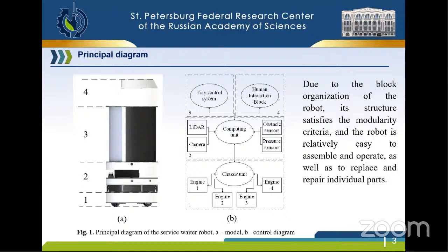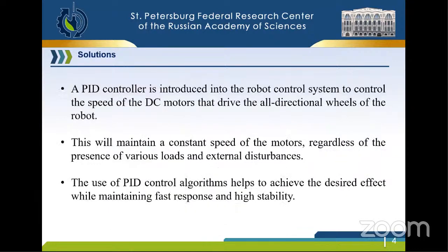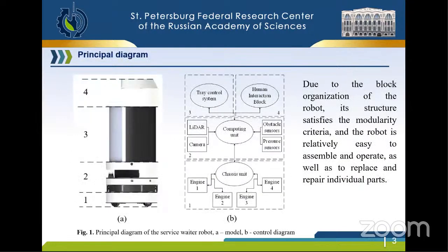And at level 4, this picture shows a sensing unit, which includes wide-angle cameras, optical sensors, and laser rangefinders, as well as pressure sensors, which are used to implement localization and navigation algorithms in the restaurant premises. The laser rangefinder is offset to the edge of the device's circumference, allowing it to detect objects around the robot, about 270 degrees. There remain blind zones, covered by 6 optical sensors.